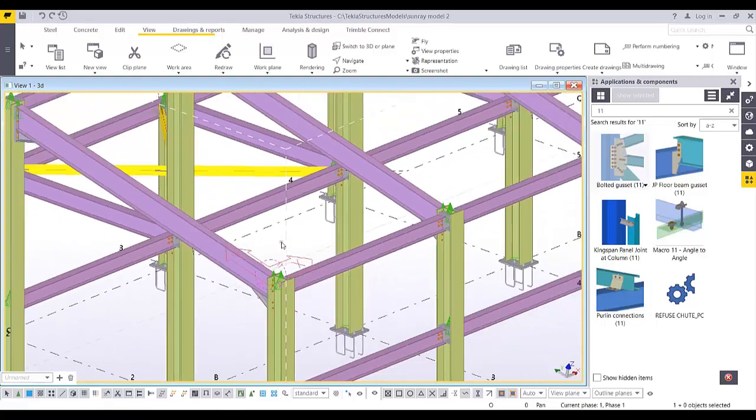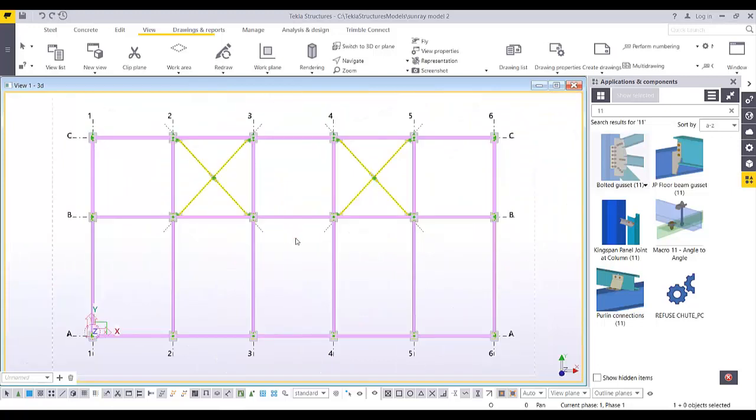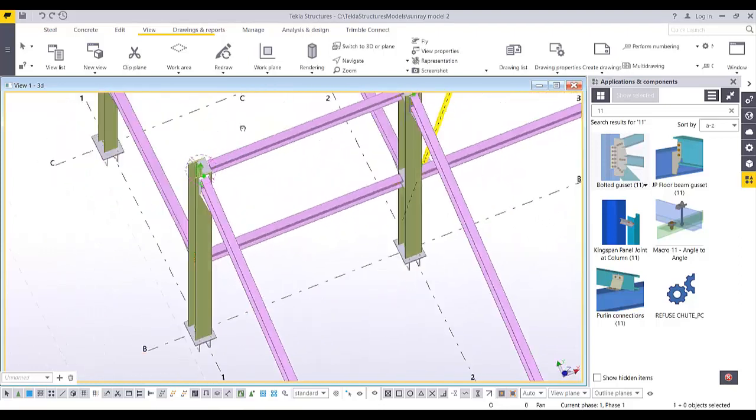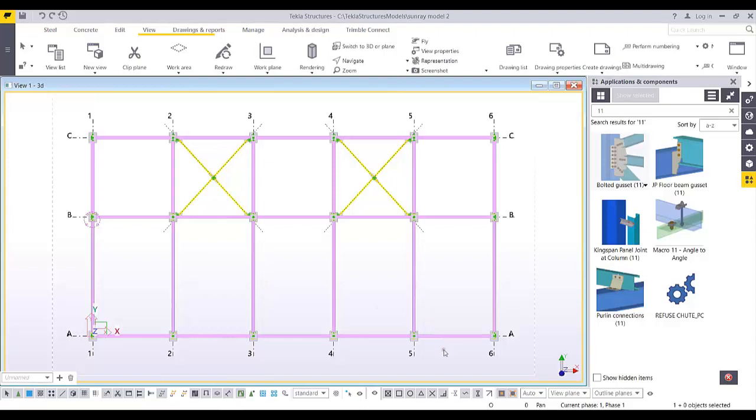So when you change the UCS, okay, Control P, this one is still not the true roof. To make this one a true roof plane view, because look, if I zoom, it's still not the true roof, right? So to make this one a true roof, you can use this work plane view.